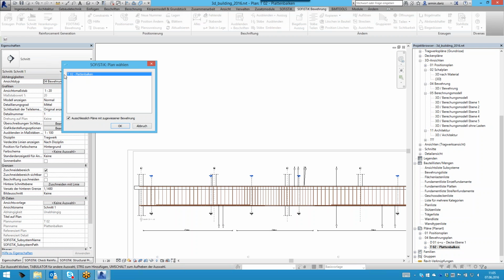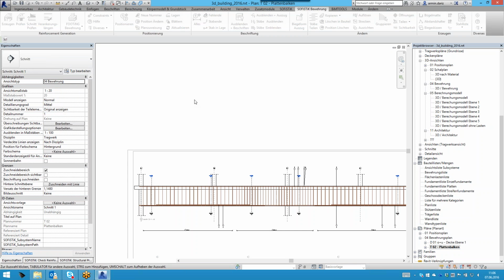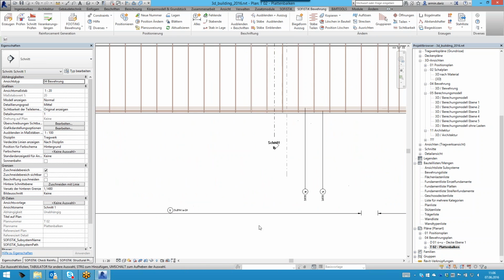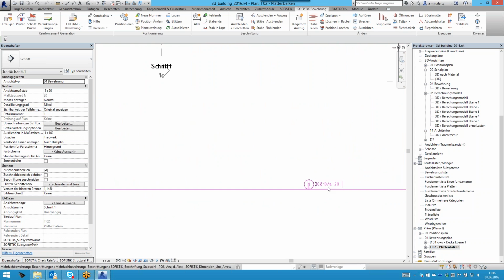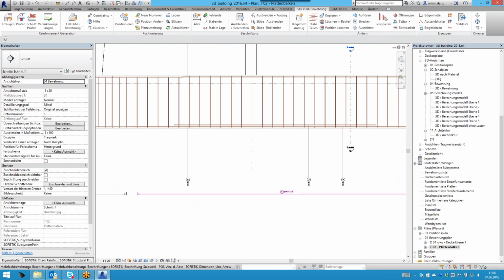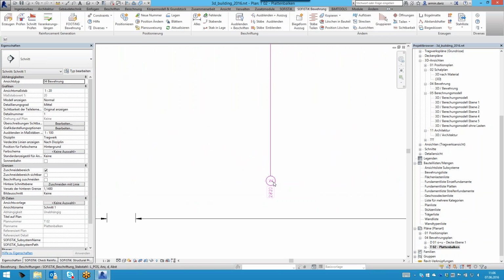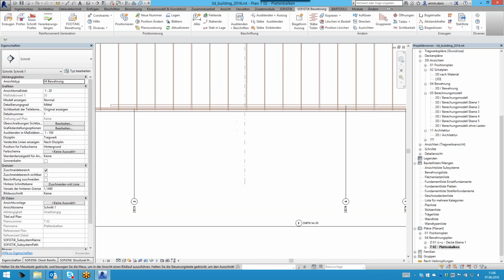And as we have discussed that we talk about a sheet-wise concept, we have to do the bar marking for each sheet in a different way. And I will do that now for the sheet of the T-beam. You see now that the geometry will be checked to see if we have the same geometry, and you can see that on the stirrup. The stirrup gets the bar mark number 1, and also this stirrup, because we have the same geometry, gets the bar mark number 1, as you can see here. The longitudinal bars get bar mark 2, bar mark 4, and 3, and so on.